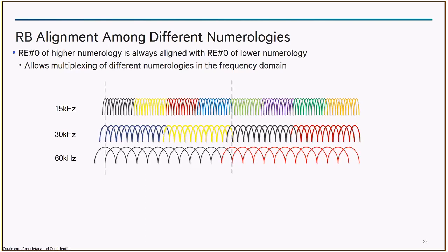And when a UE comes up, for example, Qualcomm UEs are always going to come up assuming 30 kilohertz default, and then move to 15 or move to 60. Again, I am assuming it's a standalone sort of UE. But if it is non-standalone, then there is not much. Essentially, the UE is configured with one of the SCS configurations, and it needs to stick to that SCS configuration.